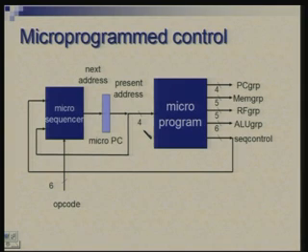Okay, in the main program PC is stepping through memory locations which contain the instructions. Here it is the micro PC, which is just a 4-bit register. It steps through different words of this microprogram memory to ensure that the right signals are generated at the right time.